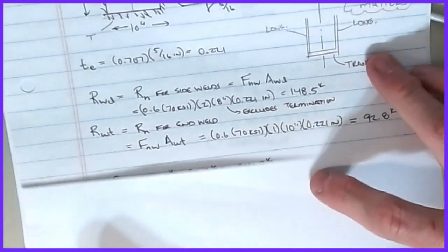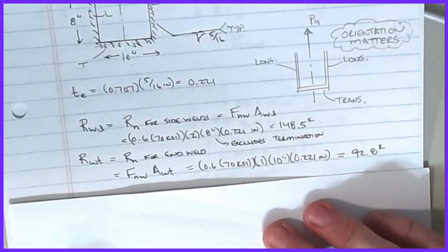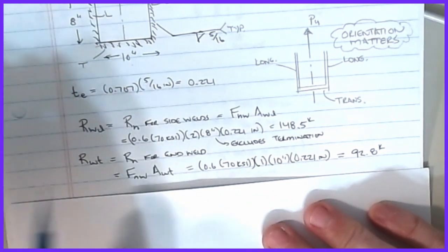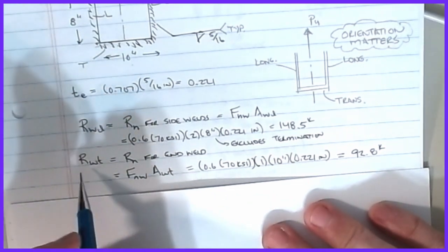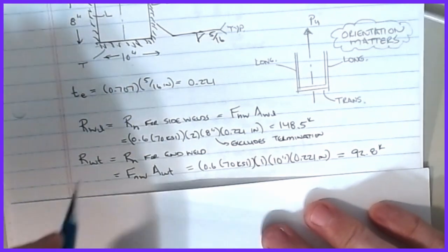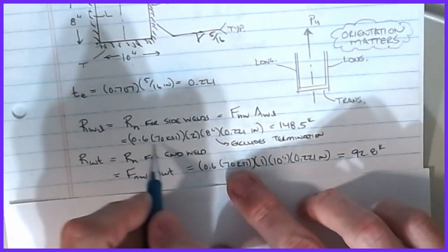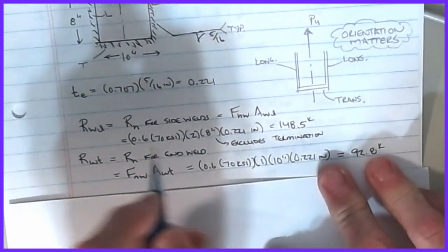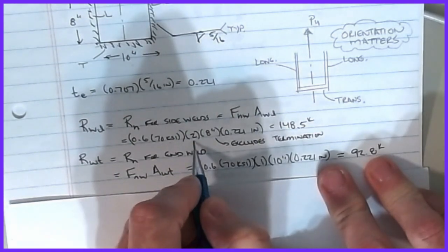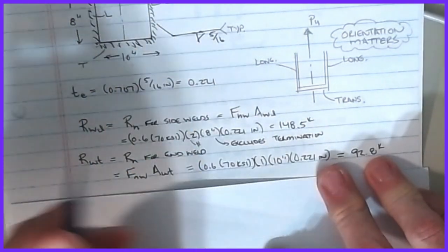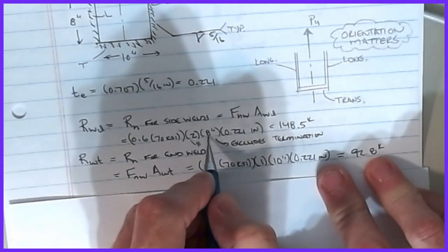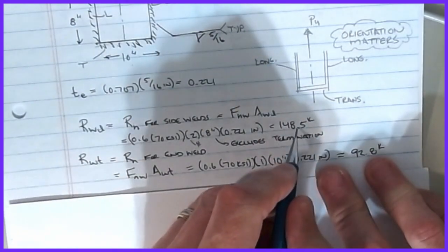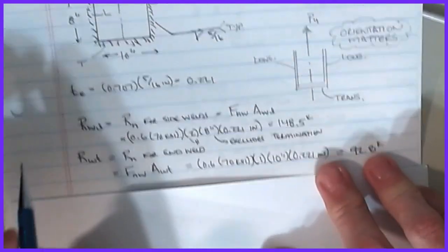And then all I do is plug in and calculate the capacity associated with my longitudinal weld, plus my capacity associated with my transverse weld. So for the longitudinal capacity, here's my 0.6, here's my FEXX, and then I have 2 welds, that's the number of welds, and a length of 8 inches on each one, and I multiply that by the effective throat of the longitudinal weld. When I do that, we get just shy of 149 kips, 148.5.